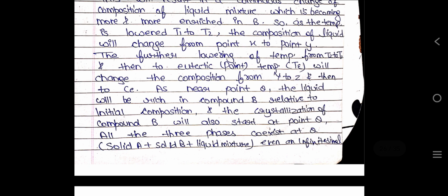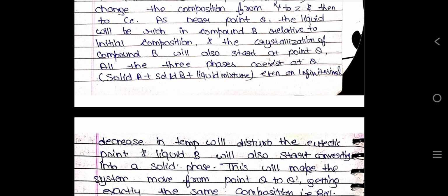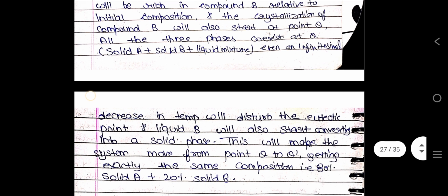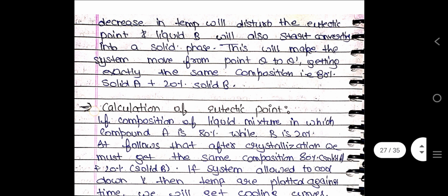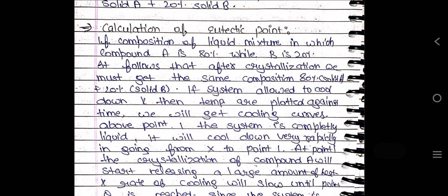Above temperature T, the composition X lies in the field of all liquid and therefore will exist as a completely liquid. When the temperature is reduced to T1, crystals of A will be initiated. Further lowering of temperature will make more crystals of A form. All this will result in a continuous change of composition of the liquid mixture, which becomes more and more enriched in B. So as the temperature is lowered from T1 to T2, the composition of the liquid will change from position X to point Y. Further lowering of temperature from T2 to T3 and then to the eutectic temperature will change the composition from Y to Z